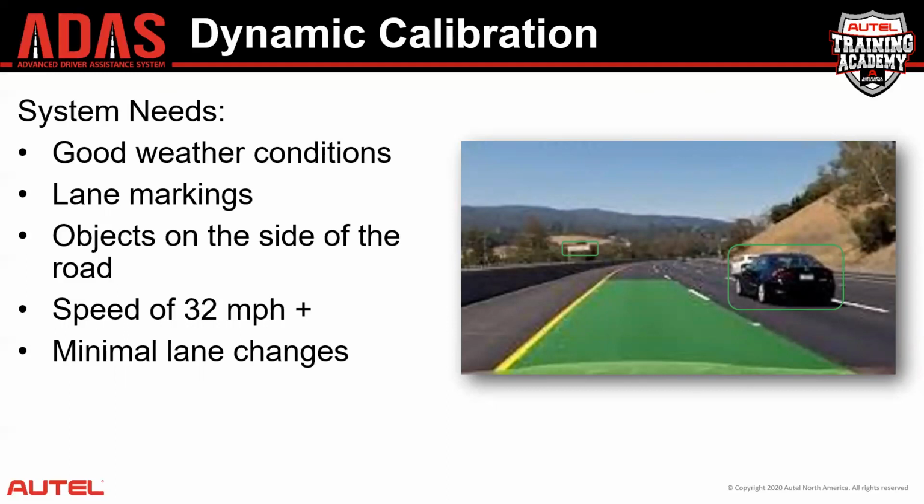Same thing holds true if you do the repair and tell the consumer to take the vehicle to a dealership. Once they leave, you are still responsible for that calibration, even though you didn't perform it. Not my opinion. It's the way the law looks at us performing calibrations in this industry.